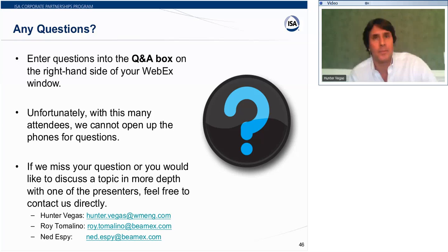But the reason people usually use seals is because they got plugging, sludge issues, that kind of thing. And so if you add a bunch of extraneous piping on the end, it's going to tend to plug up. A lot of times the reason they have a big, nice seal like that is that it doesn't easily plug. In fact, you buy seals with extended diaphragms that actually extend into the tank somewhat to try to eliminate the pluggage problem, but it makes calibrating them a lot more difficult.